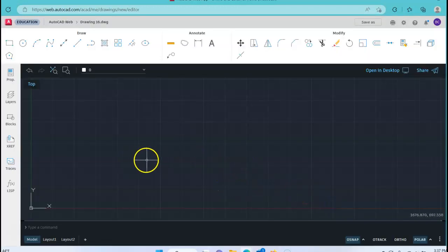Now, our very first thing to do is to take a look at this drawing and see where our coordinates are all coming from and try to determine a 0, 0 for this part. And in this case, that 0, 0 is in the lower left-hand corner of this part. So I'm going to start there with my line, and then we are going to work around to the right of that, go around clockwise on the outside, and then we'll go around counterclockwise to get these lines on. You'll see what I mean in just a second.